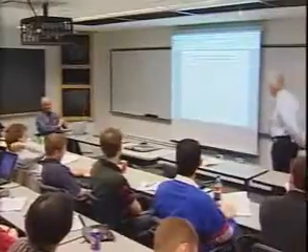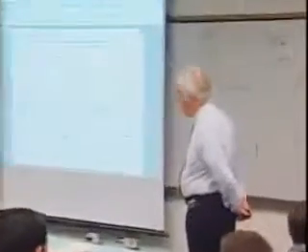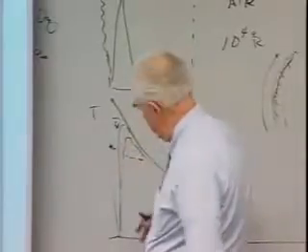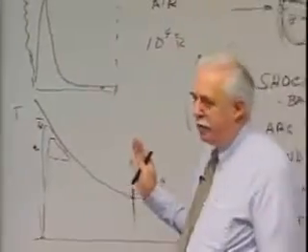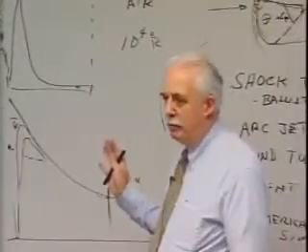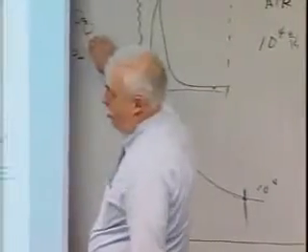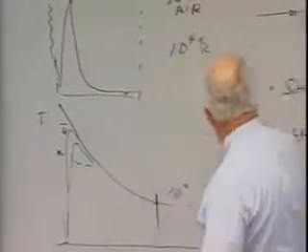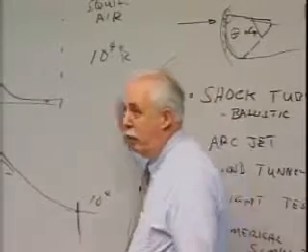Jeff, next? Yes, please. Okay, now this is the surface catalysis. I haven't really talked about that. I talked about the gas going from molecular to dissociated, ionized, to weakly ionized. When you get back to the surface, at surface conditions, you're back to a molecule again. Now, I'm simplifying things here, but I think the way to look at it is you start out with a molecule, you blast it apart, you have atoms, you get back to the surface of the vehicle, and at equilibrium now, you're back to a molecular state.